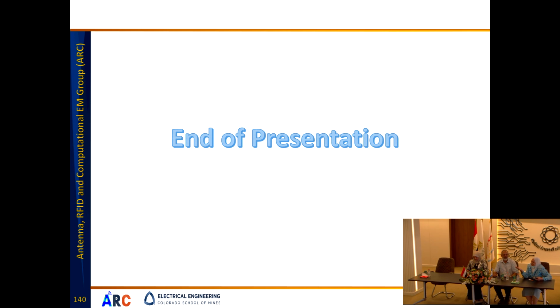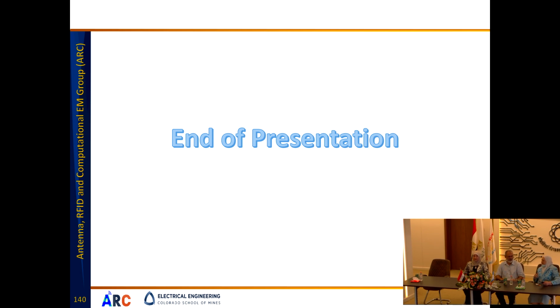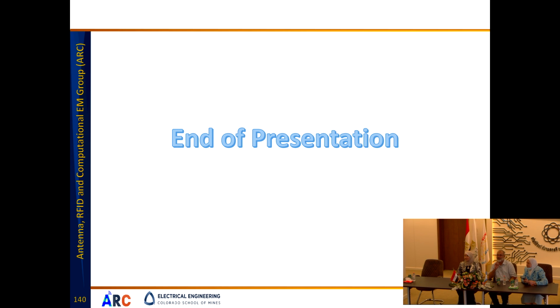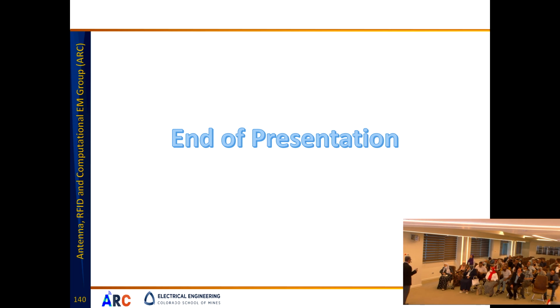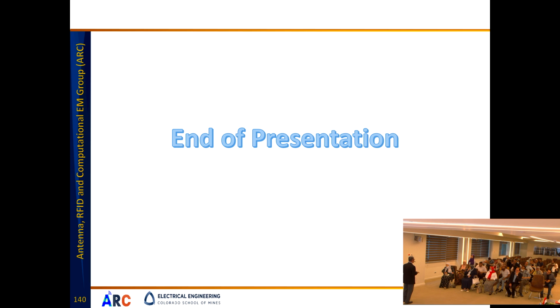Another question. Silver ink, not a perfect conductor, yeah? No. The same question. How can I represent it in my simulation? It's not a perfect conductor. For the silver ink, you can deposit it on a wider strip, and you can use a conductivity meter to see the conductivity of it before you continue with it.